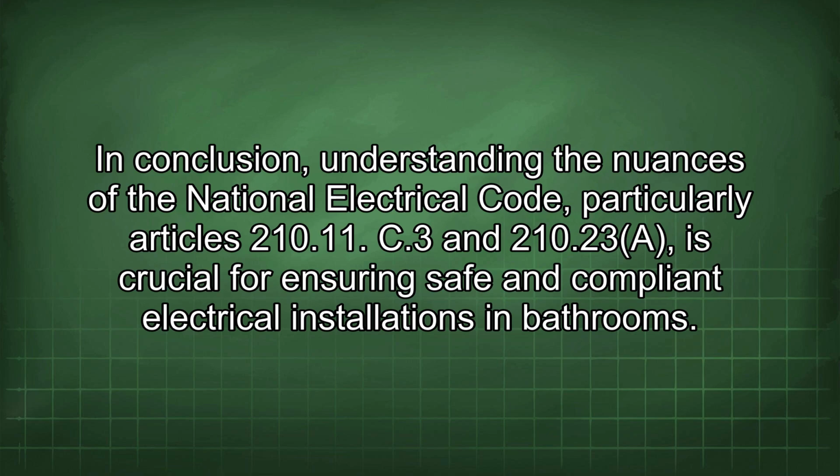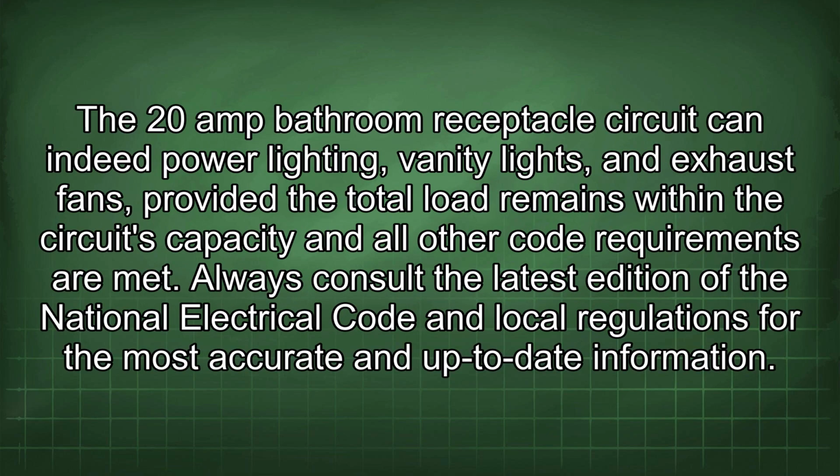In conclusion, understanding the nuances of the National Electrical Code, particularly Articles 210.11(C)(3) and 210.23(A), is crucial for ensuring safe and compliant electrical installations in bathrooms. The 20 amp bathroom receptacle circuit can indeed power lighting, vanity lights, and exhaust fans, provided the total load remains within the circuit's capacity and all other code requirements are met. Always consult the latest edition of the National Electrical Code and local regulations for the most accurate and up-to-date information.